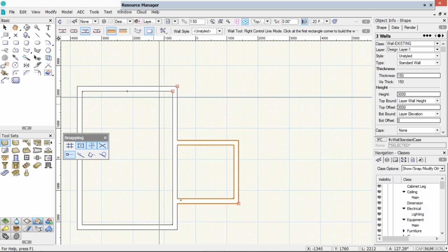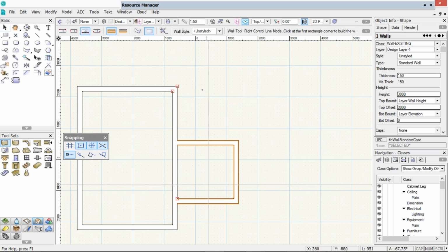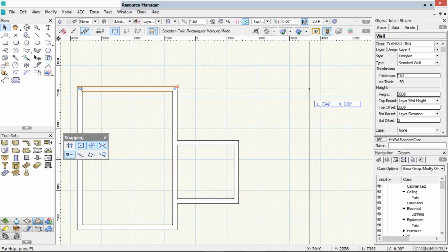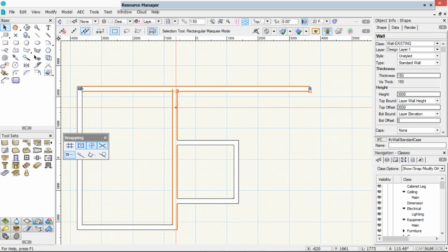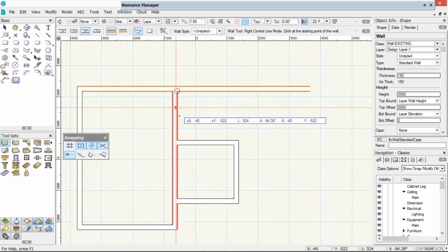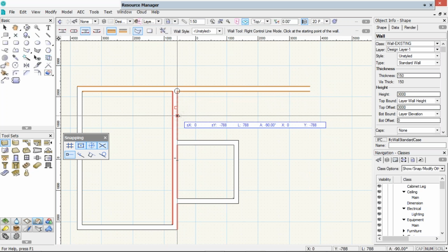Now I just need to have my dimensions as well. So I'm going to go back to my dimension plan. And I need to have a wall through here. So I could just extend that wall across here. Just take that wall out and extend it through there. I've got another wall which is offset from there. So what I'm going to do is join those two together, that one to there. I need a wall, and I know that there's a wall from this point here. I'm going to use my G key, because it creates a floating datum. So down to there, this needs to be an offset of minus 663.